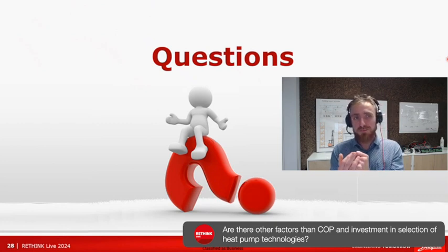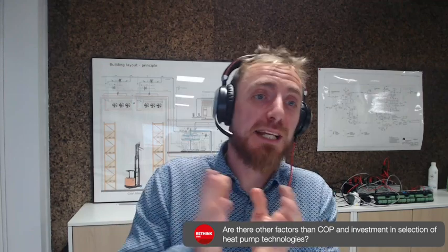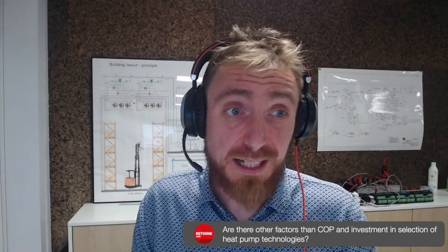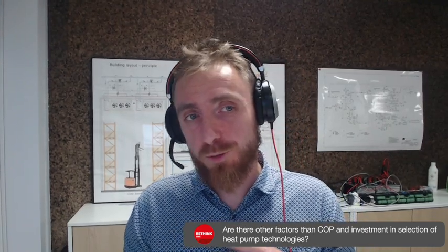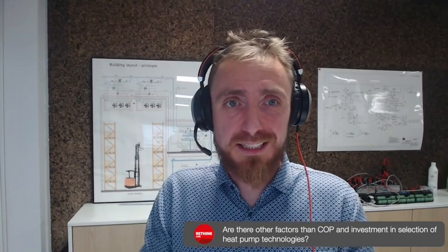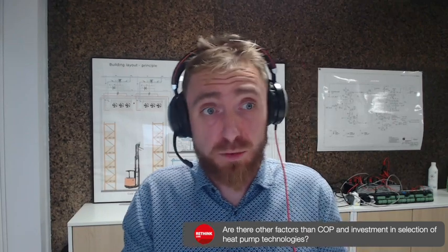COP is the first one. Not the only one, though. Next one is investment. Depending on technology, depending on the application, you can have better fits and worse fits for your system. Then legislation, obviously, you must consider what is the legislation. In some regions, it is easier to accept certain refrigerants than others. CO2 is everywhere accepted on the globe, also in most populated dense areas, which makes it really, really easy.